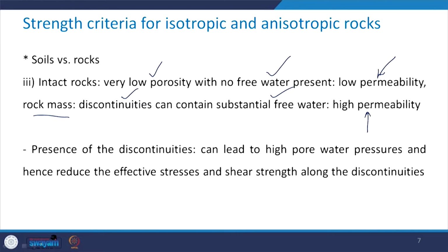Presence of the discontinuities leads to high pore water pressure, and therefore it reduces the effective stresses and the shear strength along the discontinuities. In the presence of water, the shear strength of the soil also gets altered, but the way it gets altered is altogether different from that of the rock.